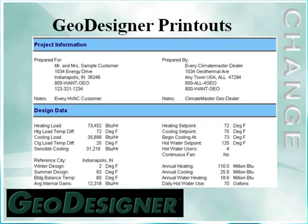We're going to show the customer what their heating load is, what their cooling load is, what our set points were, and then we actually show them the annual heating and cooling requirements in BTUs plus their domestic water heating requirement. In this case, with 4 people, it's 70 gallons per day.